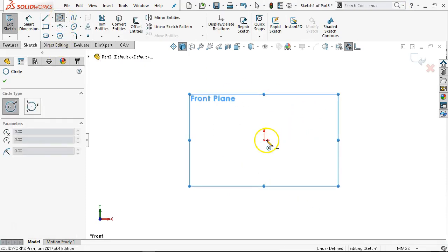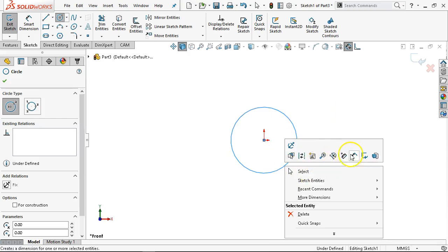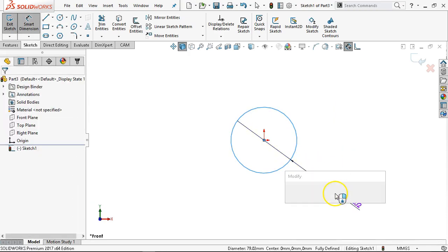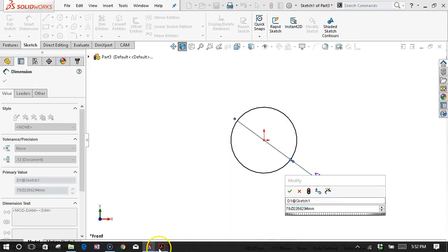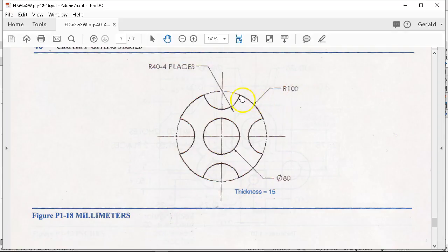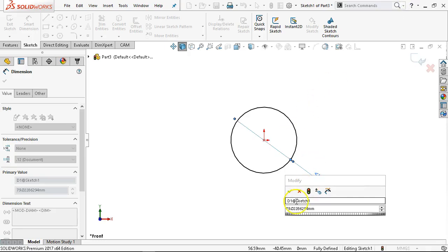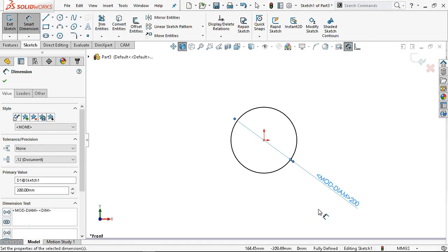Circle. Into the dimension, and we had an outside that was a radius of 100. Okay, so this is where radius of 100, because it is an arc segment, I'm drawing it as a circle and then going to end up trimming it out. Even after I trim it or whatever I do with it, that dimension is still going to stay as a diameter, or still stay as a radius. All right, whatever was in its previous state.